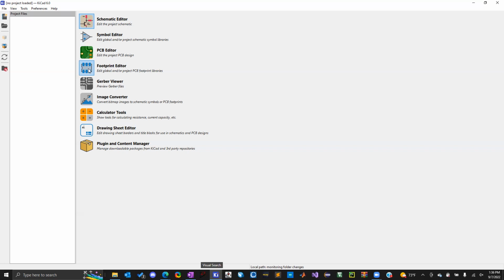Which is also usually known as surface mount technology or surface mount device. So that's SMT or SMD. They're the same thing. So the two methods are, you can either have a layer of circular copper and then a hole drilled through, and then you can take the resistor components that you're mostly used to for breadboards, and you can put them through the holes, and then you can solder them to the board, and then you cut the remaining leads off.